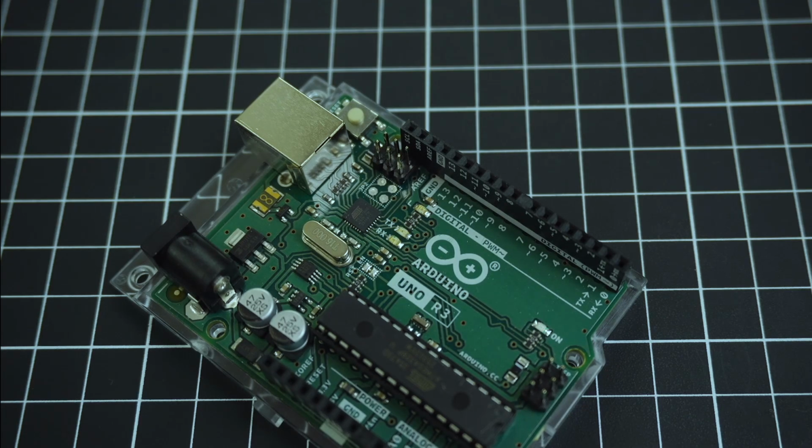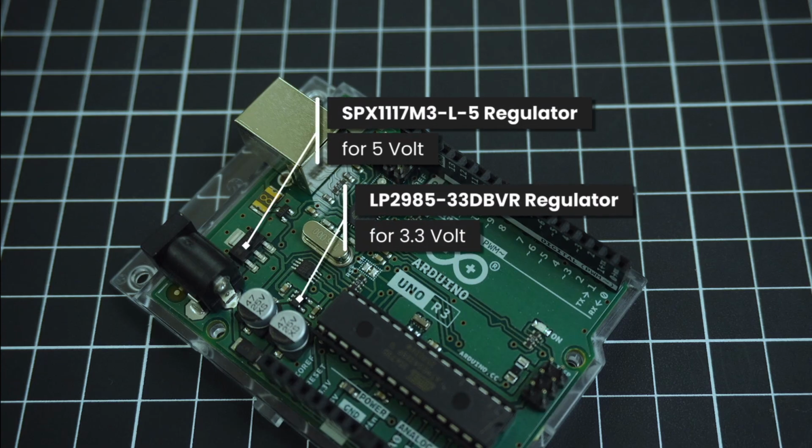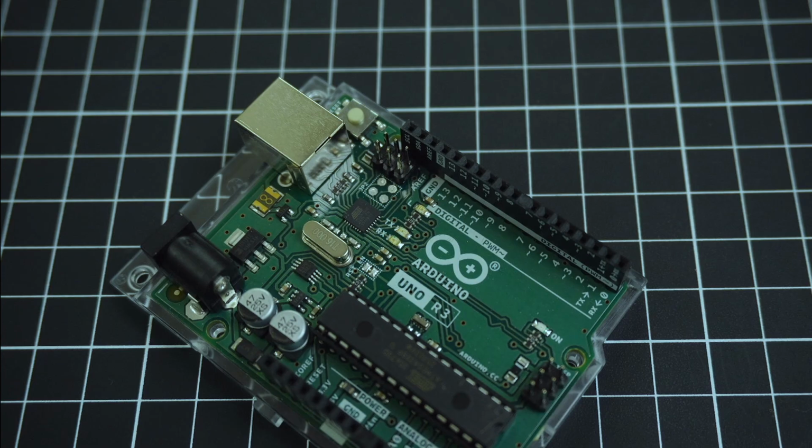Near the DC power input section, there is a protection diode that functions as a rectifier. Its primary role is to protect the board from reverse polarity, and it is also suitable for converting AC power to DC. This helps safeguard the board from potential damage. The 2 voltage regulators ensure that the board receives a stable 5 volts and 3.3 volts for reliable operation.